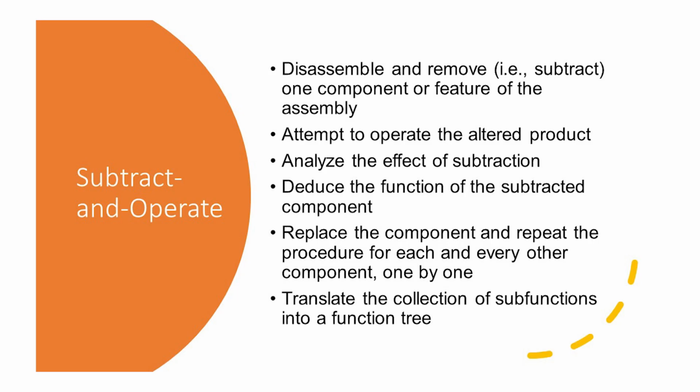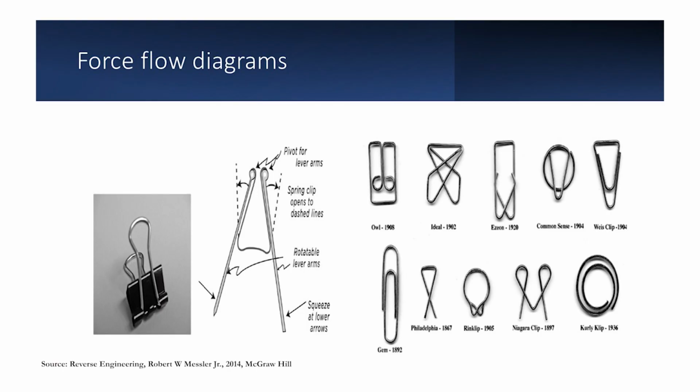Or maybe after learning about the sub functions, you may come to a conclusion that some of these functions are not needed for your own product, and so you get rid of those parts and you make a more compact or a design that is maybe cheaper or functions better. So, a critical part of reverse engineering is to create these force flow diagrams.